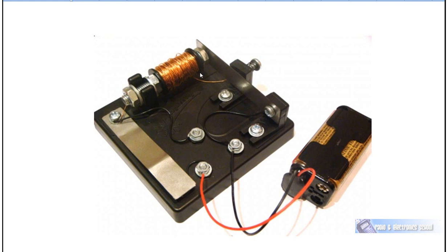When the current is turned off, the electromagnet is no longer a magnet and the armature springs back to the spring, and of course that makes the circuit again, and the electromagnet is again switched on. So in effect, this armature just buzzes. It's a buzzer. And if we wanted to, we could extend the armature and put a little bell here, and instead of having this sort of armature, we could extend it with a little ball on it, and that ball could ring a bell, and then we would have a bell.